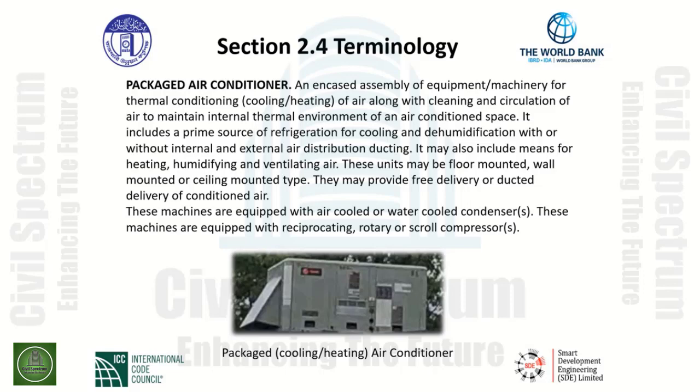These units may be floor-mounted, wall-mounted, or ceiling-mounted types. They may provide free cooling or ducted delivery of conditioned air. These machines are equipped with air-cooled or water-cooled condensers. These machines are equipped with reciprocating, rotary, or scroll-type compressors.